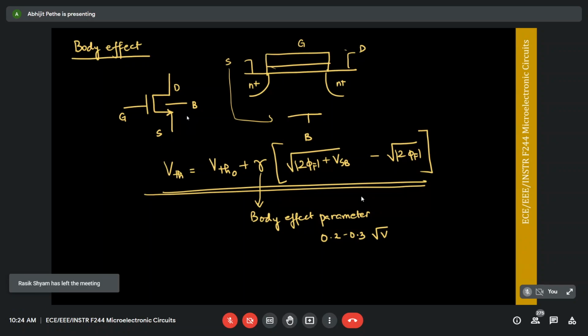Now, people figured out like 20 years ago that we can use this to electrically change the VTH. So in a lot of digital designs, we use this to modulate VTH. But in the last 5-6 years, nobody uses this in FinFET models. In the old technologies, people continue to use it, but in none of the latest technologies do we really worry about the body a lot.